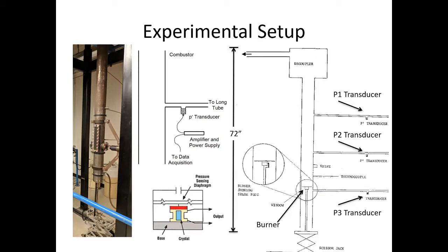to atmospheric pressure. The burner plate could also be elevated up or down to position the flame inside the Rijke tube. This was used in the experiment to observe how the position of the flame affected the acoustic waves inside the tube. 3 different positions of the burner plate were observed: one at its original position, marked as 0 inches, one at around 2.5 inches, and the last position at 5.25 inches. In addition, in one case where the burner plate was located at 0, the valve was also opened.